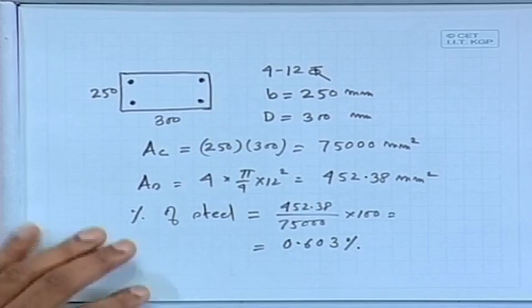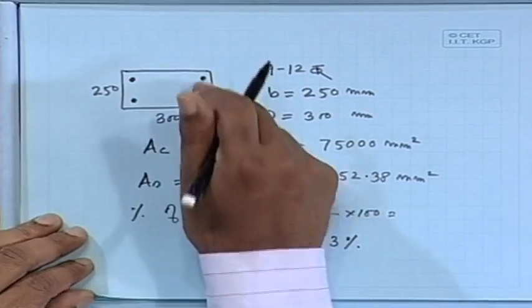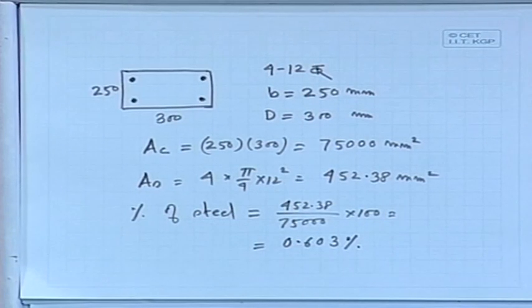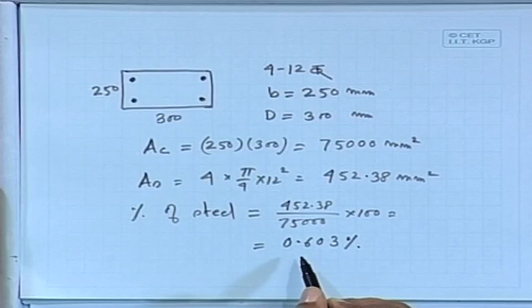So, even if this section can take the load you apply, we cannot provide this section with this reinforcement because it is less than 0.8%.